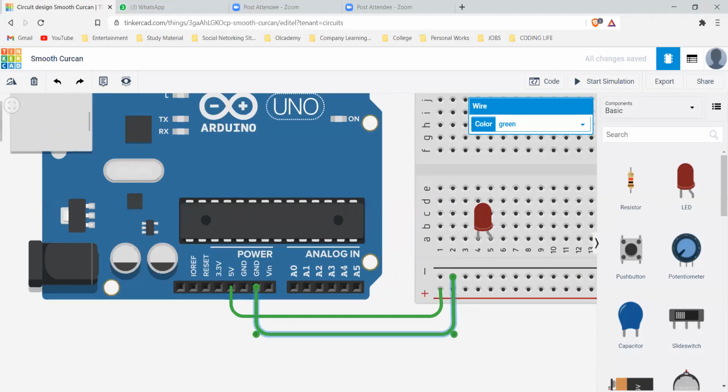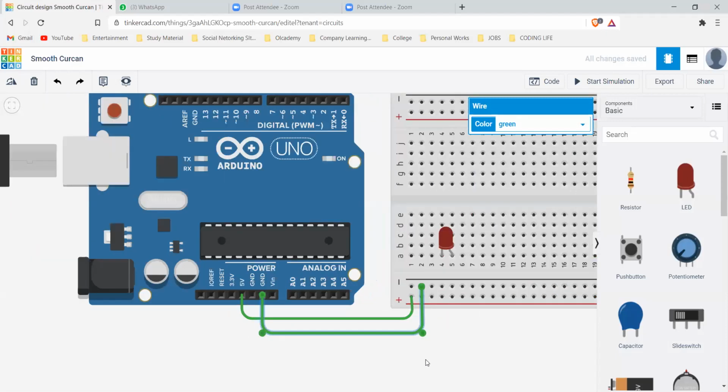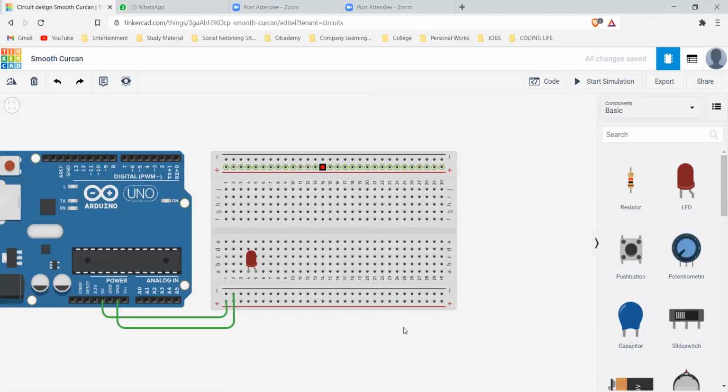Okay. Now, what if I tell you that you need to use not only the circuits below, but above as well? So you need power to these. So you need to connect the positive to the positive and the negative to the negative. Always use these to connect further. So you can just connect the positive to the positive right through here, and the negative to the negative. So what this did is it just provided you power to the entire circuit.